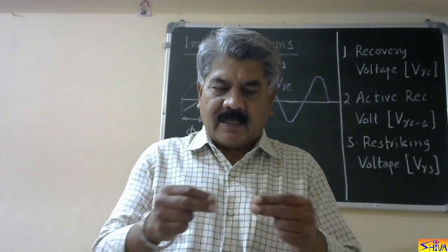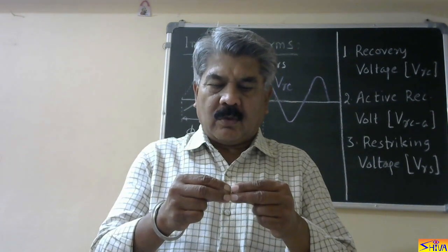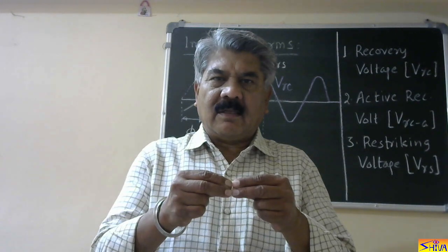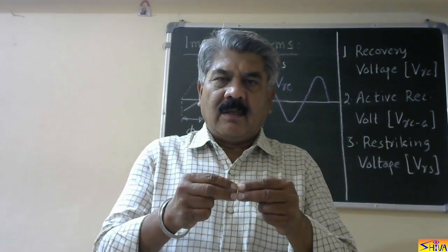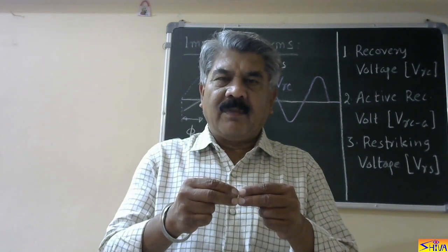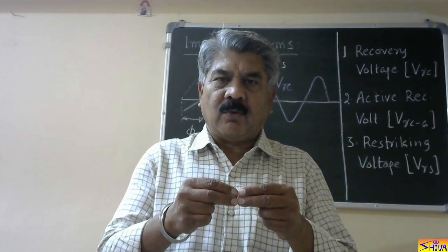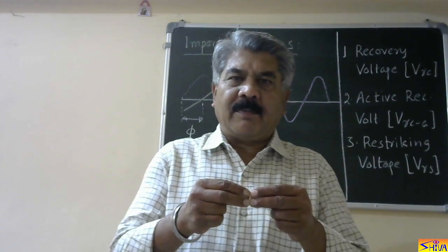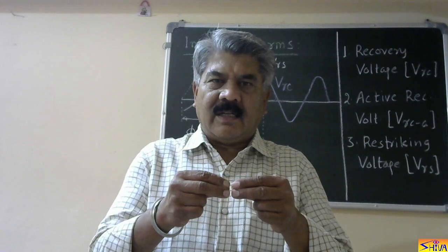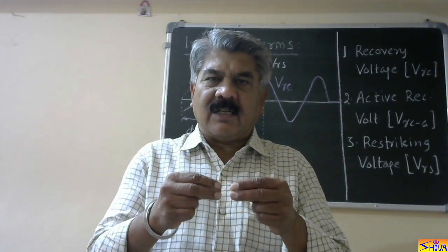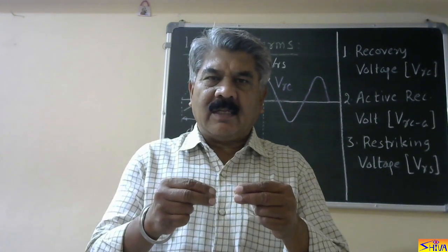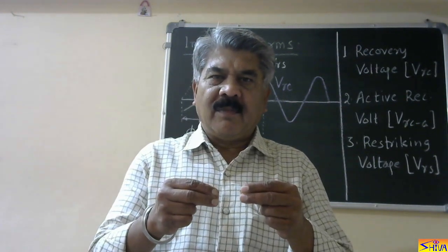Now the circuit breaker consists of two poles or two electrodes. They are engaged like this. In normal condition, load current flows through these contacts, and when there is a short circuit, fault current flows through them. When the trip coil is energized, they start separating. One contact is fixed, another is moving. So there is a transition from current carrying to voltage withstanding state, and due to this, an arc is developed between the electrodes.